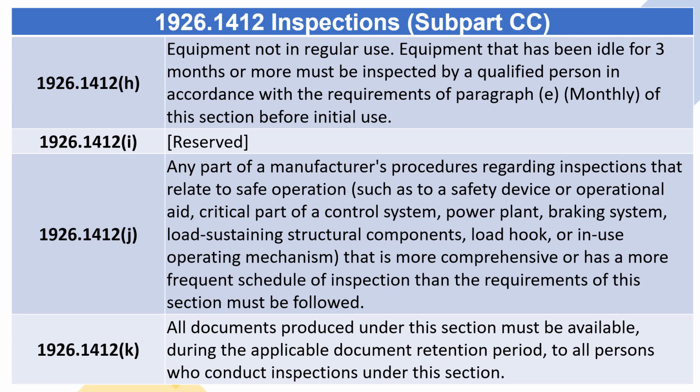1926.1412 H. Equipment not in regular use. Equipment that has been idle for 3 months or more must be inspected by a qualified person in accordance with the requirements of paragraph E, monthly, of this section before initial use. 1926.1412 I. Reserved.